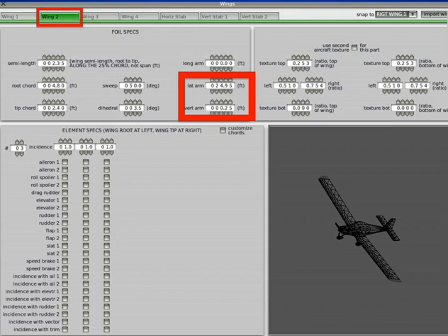There's also the cost issue on this. So let me explain what I mean by different functions. If you are a race aircraft, you want to go as fast as you can possibly go. Lift is not a big concern. You've got a big engine that's going to pull you right through the air very quickly. So you're worried about drag. Well, long wings also give you drag, so you'll get rid of that. You might want to be more maneuverable. Fighter aircraft have short, stubby wings. Look at all the World War II airplanes. They all had short aspect ratios.